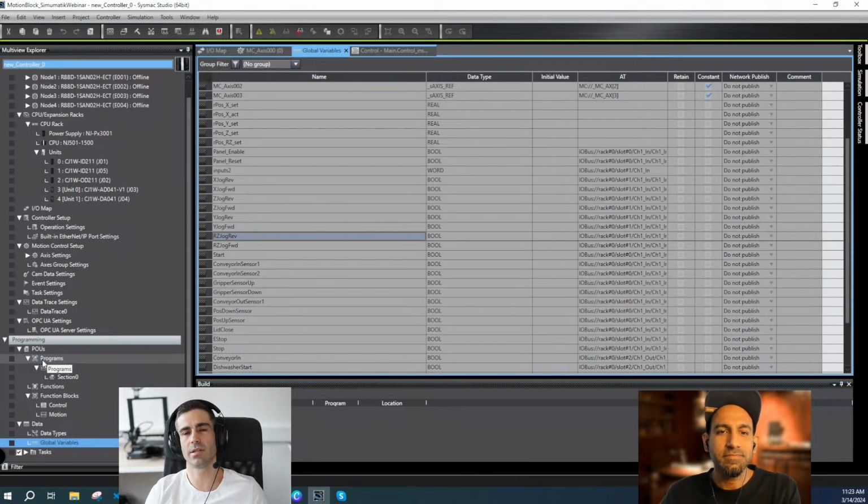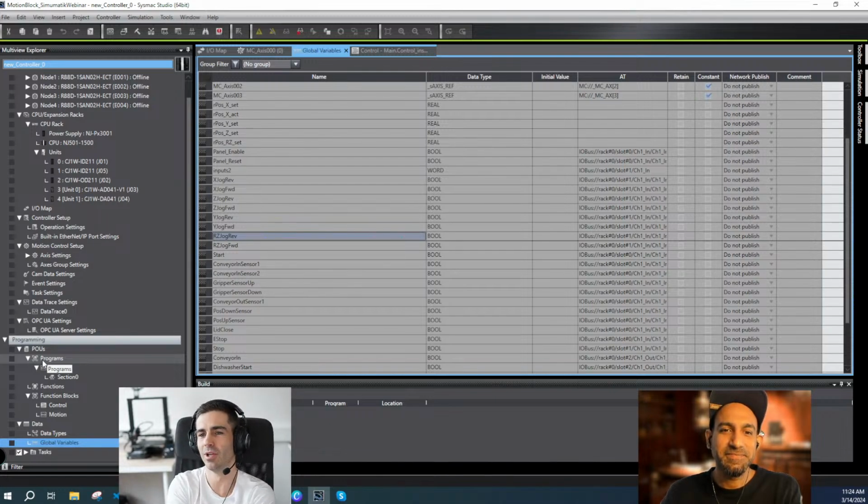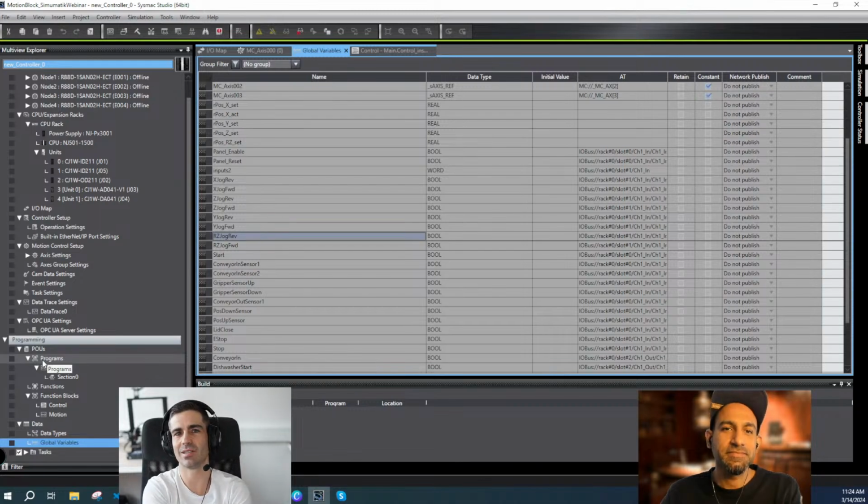Since the IEC standard, I think most of the manufacturers are coming closer to the IEC standard. And the languages are defined. There are some rules. Of course, not all of the manufacturers are 100% compliant with the standard, but mostly, I would say, structured text is the easiest language to port because it's just text-based. The others are the diagrams and so on. I would say maybe it's not that easy, but with structured text, that's the benefit, that you can copy-paste it. And I would say you could move the structured text code from one platform to the other pretty easily nowadays.